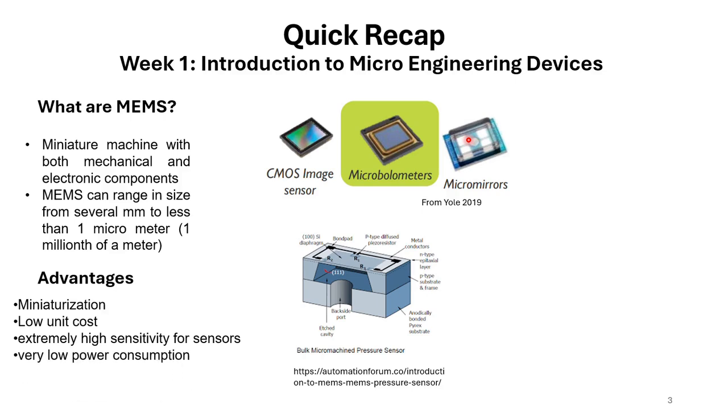Another advantage is that MEMS sensors have very low power consumption. They consume very little power, and many of the MEMS sensors can be fabricated using a CMOS compatible process. So in the fabrication itself, we can integrate MEMS with CMOS circuits. It provides a platform for ready integration with microelectronics. Most of the MEMS devices have to be integrated with microelectronics to get a system.